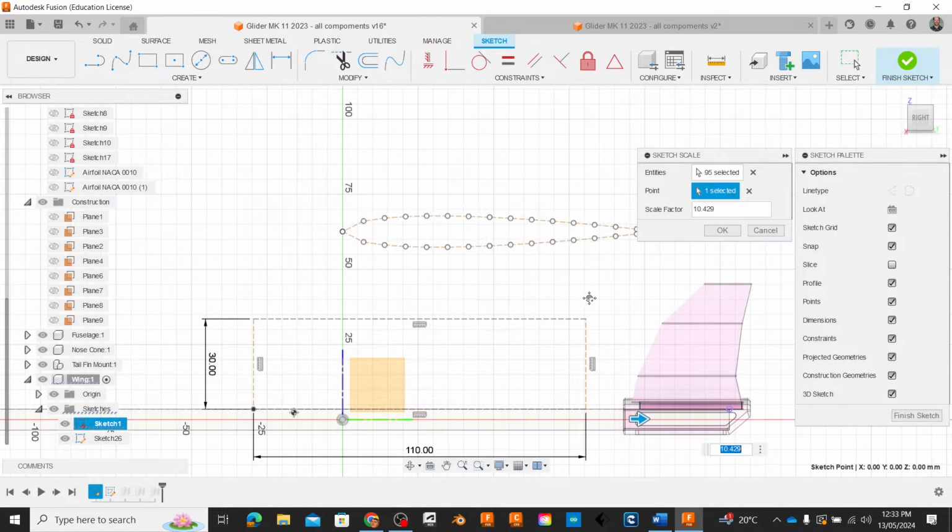All right, so what I might need to do here is make a point. So if I go down to create, sorry guys. So if I make a point here below that point I want to move it to, it should work for me. So select that profile sketch again, making sure you have enough room.